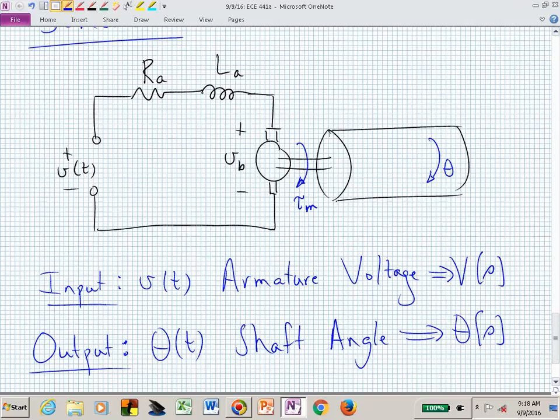We will actually model this via two subsystems. We have our electrical side. Obviously, you can write a KVL equation for that circuit. And then we will have the mechanical side, which is no longer translational. You're good with masses and springs and dashpots. Now we want to do the same thing for rotational inertia. Instead of translational systems, we now have rotational systems. But again, that's a mechanical system, and they're coupled by this essentially dependent voltage source that occurs because of that shaft spinning in this magnetic field.